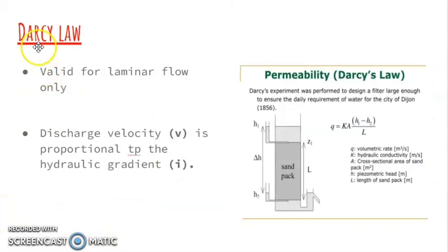Okay, what is Darcy's law? Darcy's law is valid for laminar flow only. The discharge velocity is proportional to the hydraulic gradient. Darcy's law is based on Darcy's experiment, and the equation is Q equal to KA(H1 minus H2) divided by L.